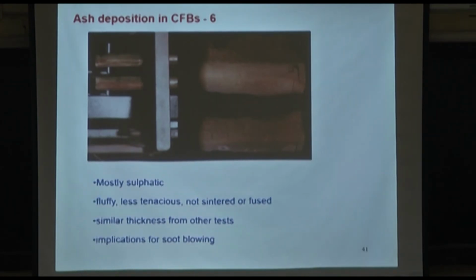So we looked at what these deposits consisted of through SEM-EDX. These are mostly sulfatic, which is very well known: the sodium sulfates and calcium sulfates. These have low solidification temperatures, and they are forming on the ash particles. Those ash particles were forming in here.